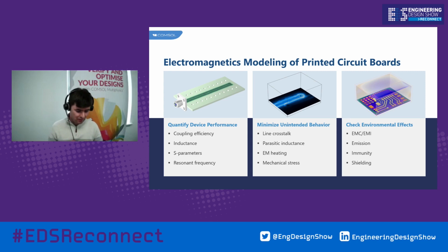The final thing we might want to do is look at the interaction with the environment. So this is sometimes referred to as EMC or EMI. So this might be looking at, is my PCB emitting electromagnetic radiation? And trying to keep that below some standard, perhaps, or equally, if the environment contains electromagnetic radiation, is my PCB immune to that radiation? So can it function despite that? And sort of similar to immunity is shielding, so designing some kind of shielding setup so that my PCB is shielded from the electromagnetic environment that it's in.